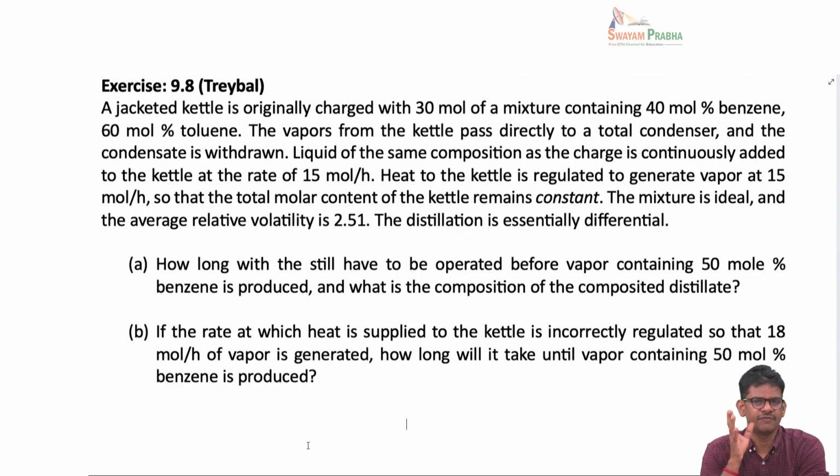So that means we need to find a way to determine how the vapor coming out of the still varies with time, and also keep in account this new stream coming into the vessel. So what we actually need to do, we cannot directly use the Rayleigh's equation we derived before, which was the case for a batch system. Here now we are changing the operation completely. So we have to go to the basics.